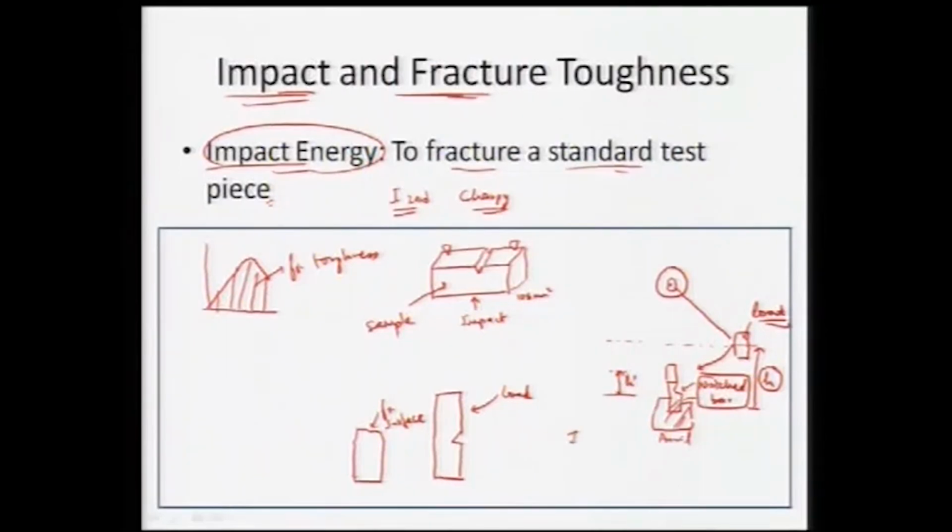It can be provided either in joules or foot pound, or Newton meters. Newton meter comes to be joules. Generally the energy provided here is around 20 joules, or 15 foot pound, which is basically the minimum requirement for a particular material for certain engineering applications.